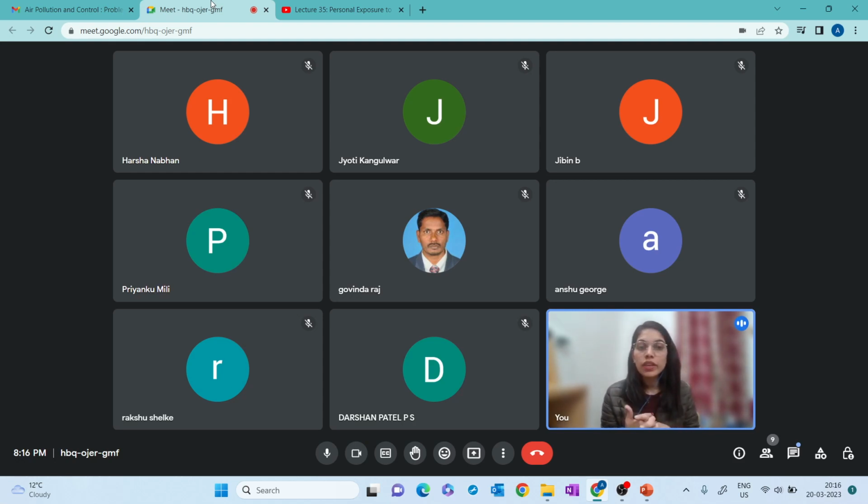Now, when we collect a 24-hour or 12-hour sample, what we do is that we have this low volume or high volume sampler. We put the filter on, we let it run for 12 hours, then we go collect the filter. So the filter has the deposition, but it's a 12-hour accumulated deposition, right?